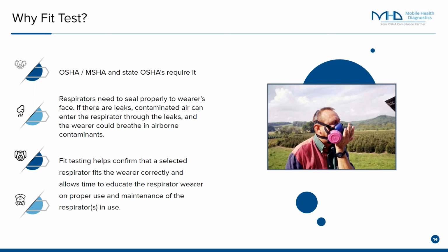Making sure that the employees are wearing a respirator that is sufficient for the environment they're going to be working in is really important. And fit testing can help ensure that they not only know how to use the respirator, but also understand the conditions to use it and how to properly maintain it, so that when they are in a condition that requires it, it's being used properly.